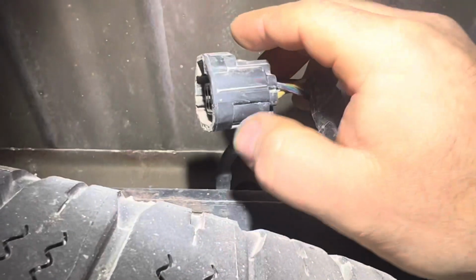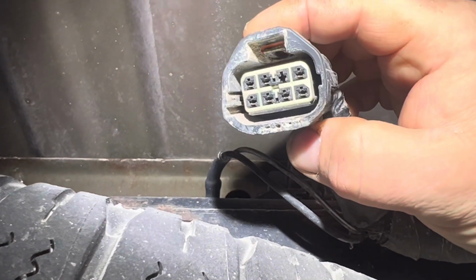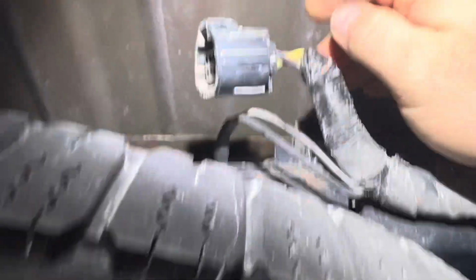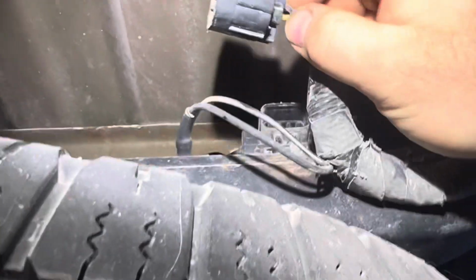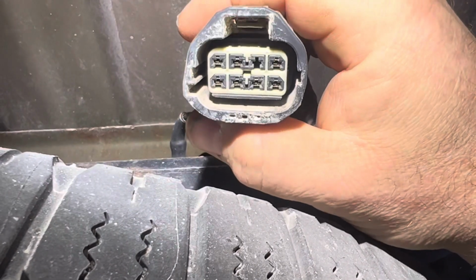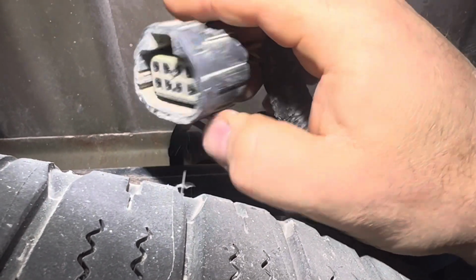They actually made this kind of easy. I don't know if there's a right way to do it, but this is my way. I've done this before. Only on that module, everything was set flat. This one is double stacked. I'll show you why that matters. Here we are underneath the truck, and I've got this driver module unplugged. It sits right here on top of the spare tire. They used to be a lot harder to get to. This one's not too bad at all. And you can see that's a double stack plug.